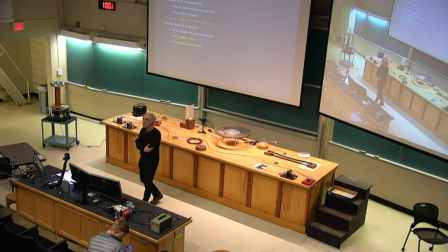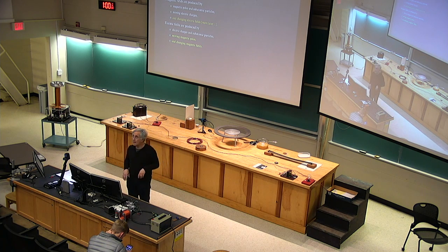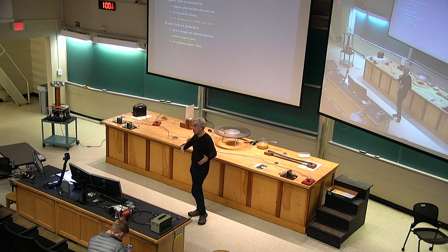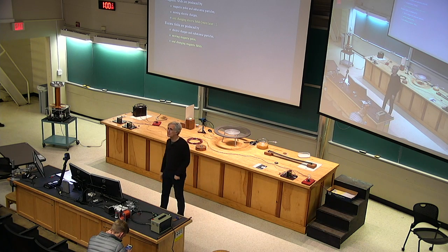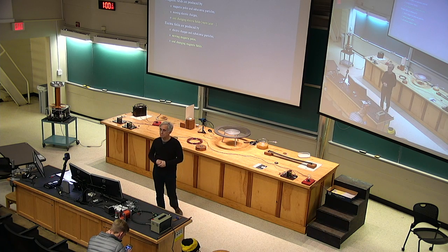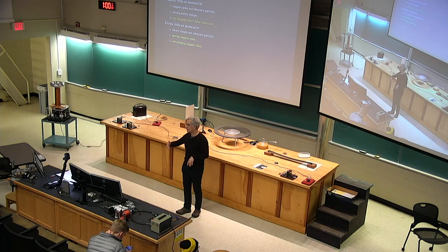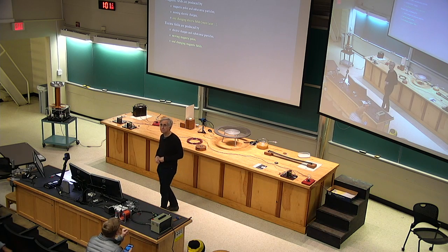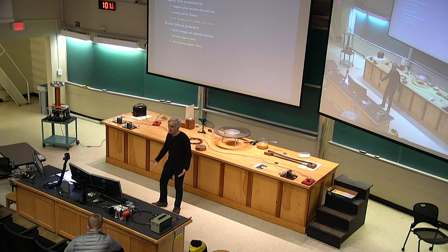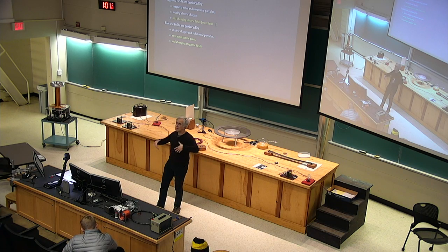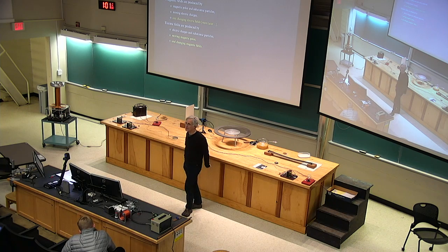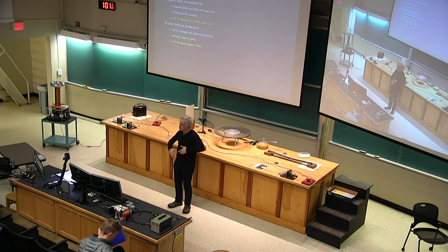So where things stand, I'm trying to explain to you how power is moved across the country, across the neighborhood, into your house, how electric power does that. It involves multiple circuits and moving energy from circuit to circuit because of these issues of voltage and current. High voltages are great for delivering power efficiently because they involve sending relatively little current through wires, and wires waste energy according to the current that flows through them.